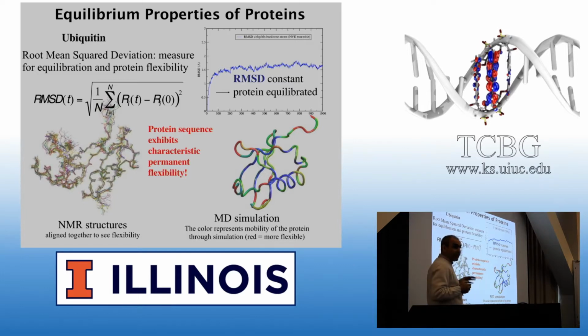So that's a good way of initially looking at the system, showing that, okay, my system seems to be stable. It seems that nothing crazy is happening. The protein is not falling apart. But if you see something happen here, for example, a great RMSD change or going up and down, then you have to dig in deeper and find out what that is. You can play with different flavors of the atom selection to gain information.